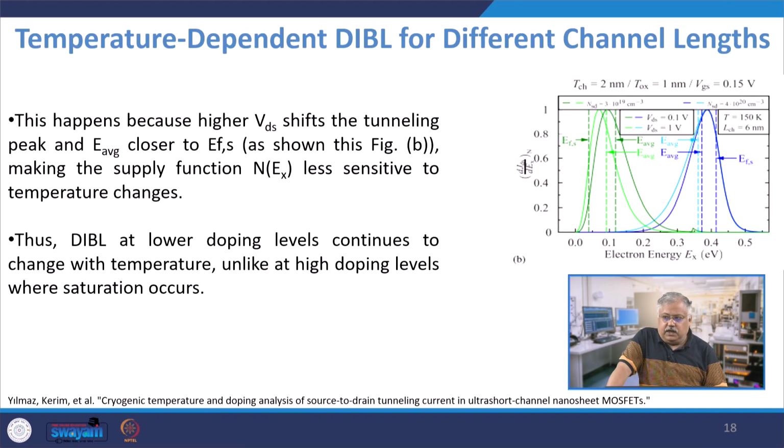So with this, let me recapitulate what we did for the next half an hour here. We looked into temperature dependency of the DIBL and thermionic effect, and subthreshold slope. Two short channel parameters are affected by the doping concentration of source and drain. We also looked into the temperature dependency of various second order effects which come into the picture. And we saw the dependency of thermionic emission and tunneling with respect to temperature in this subject.